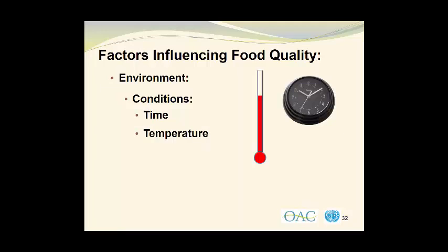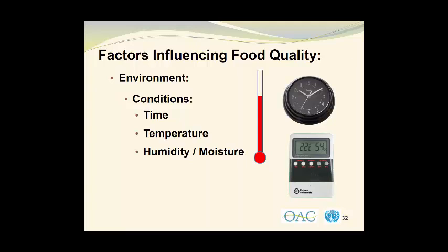We look at the temperature of the storage. Is the temperature excessively high, which will accelerate decomposition, or has it been chilled, which will help maintain quality? What is the humidity in the environment? And here you see a small meter that is designed to record the temperature, which is 22 degrees Celsius in this case, and the relative humidity in the air, which is 54%.